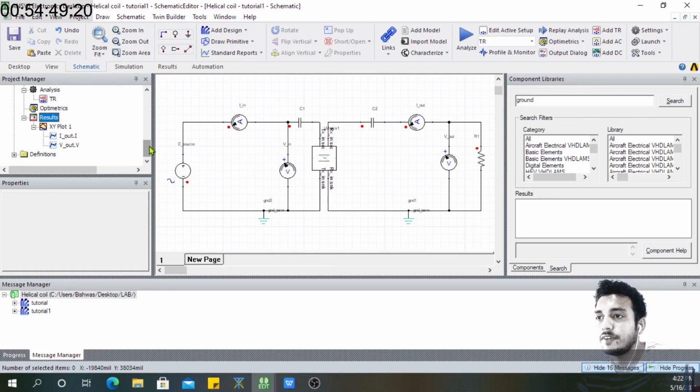So you need to specify, yeah, you need to calculate losses, and then that solver will give you the ability to see the losses, but it will take a lot of time. If you want to do that for your real project where your coil might be a lot bigger, I tried it sometime before. It took me almost a week. I ran that in my laboratory day and night. Maybe the frequency sweep that I did was too much, right? The steps I was taking were too many.